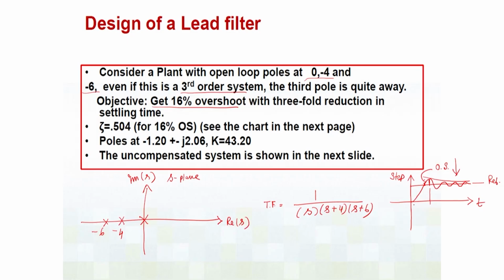Now, what is the settling time? Well, settling time is when this amplitude comes down, with respect to the reference signal, to within, say, plus minus 2% of the value. There are 2 ways to define it: some groups use plus minus 2%, some use plus minus 5%. So, settling time is this time. This is the settling time Ts and it is generally written as 4 over zeta omega n, where zeta is the damping and omega n is the natural frequency of the system.